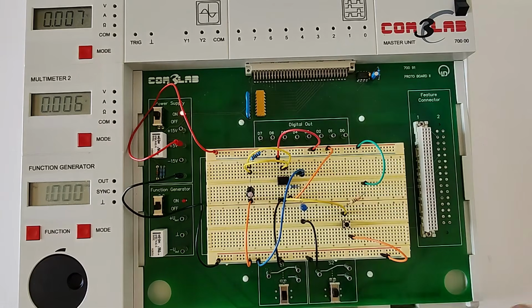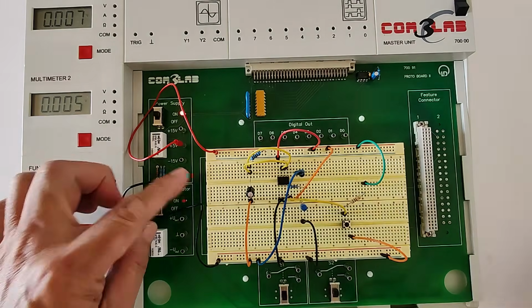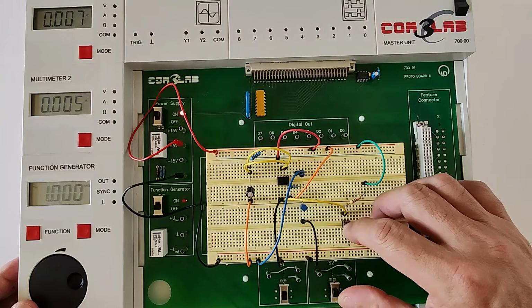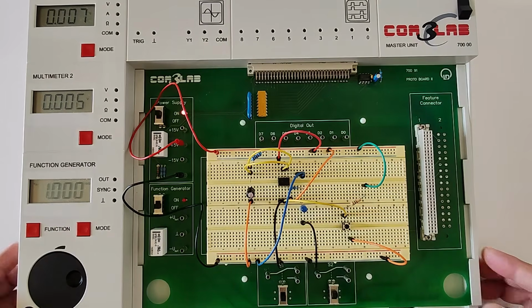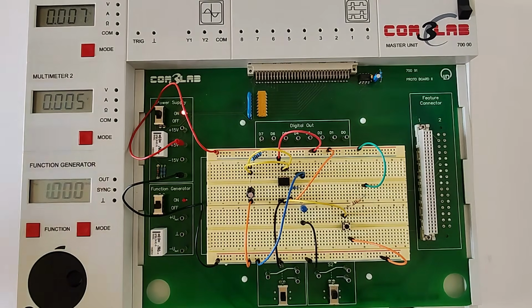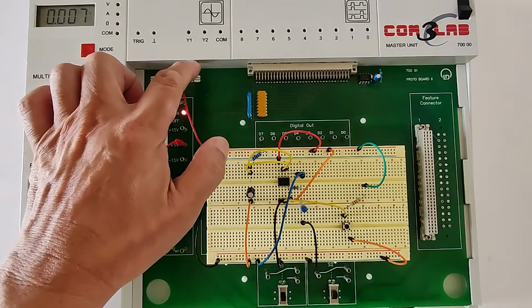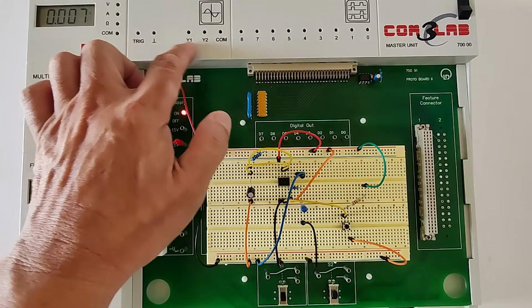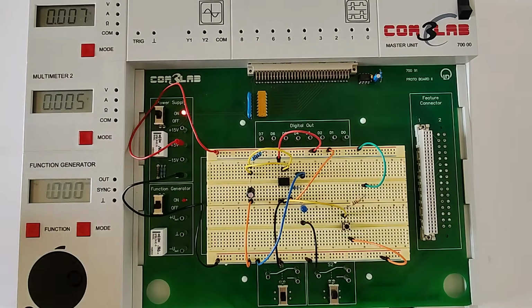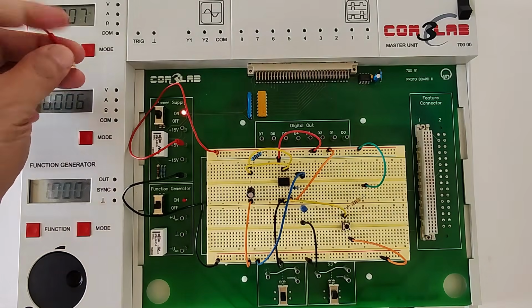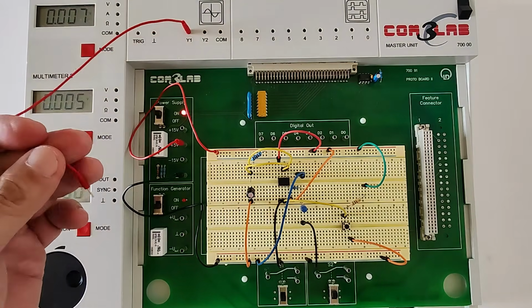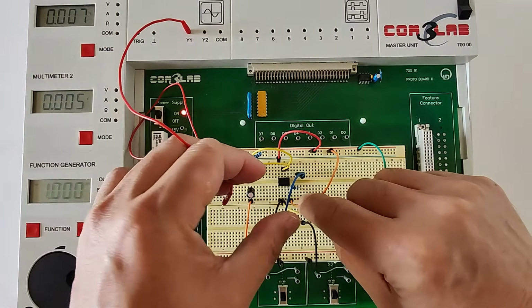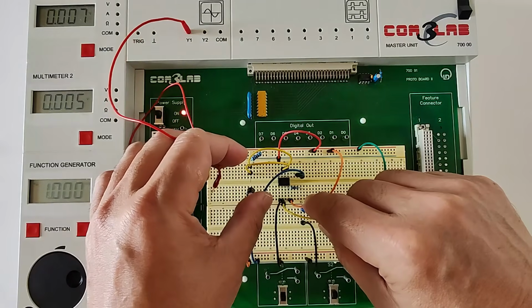So here, let me return the original 47 microfarad capacitor. So there, a little over a second, it's on. Okay, now, to see that waveform discussed in the theoretical discussion, I need to connect the oscilloscope here at the top. Just like in the previous video, the oscilloscope connection will be something like this. Y1 will be connected to the output. Output of our 555 timer is pin number 3. So I need to connect it to pin number 3.